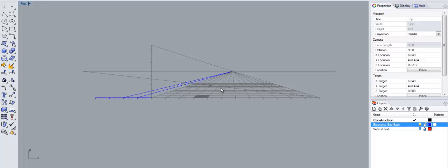The second thing we need to note, and I didn't talk about this in the last tutorial, is that wherever you take the picture plane, that's where everything is obviously going to be at scale, so it's going to be perfectly measured. The farther away you get from the picture plane, the more distorted your image is going to become. So you want to make sure you make that cut in a very intelligent location.